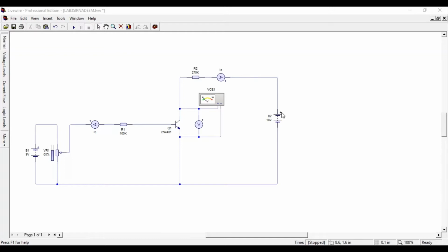We want to measure the IC current to determine whether VCE or IB has the greatest effect on IC. We will measure when the ammeter is at 0 ampere, 25 microampere, and 50 microampere. The potentiometer is used to set the ammeter value, and this resistor ensures that the base current is always low, to avoid transistor damage from excess supply voltage.